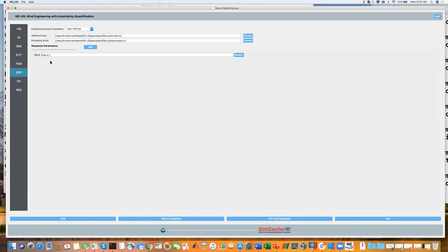So here's what I'm going to do. Again, different. Instead of getting all that output that we saw in the 9-story building, I'm just going to look at, say, the nodal displacement. And all I care about for this result is what's happening to the displacement of the roof. If I want, I could add, say, root mean squared acceleration also at the roof. And just for the fun of it, let me add the force at the element at the base, and I'm going to get the shear force. I could also ask for the moment if I wanted to, which would be the base overturning moment.